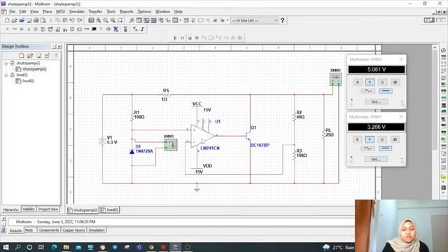The op-amp acts as the comparator in this circuit. When the output increases, the sampling circuit will send a feedback signal to the comparator. Then the control signal will decrease the shunt current and there will be less load current. And lastly, it will keep the regulated voltage from rising.